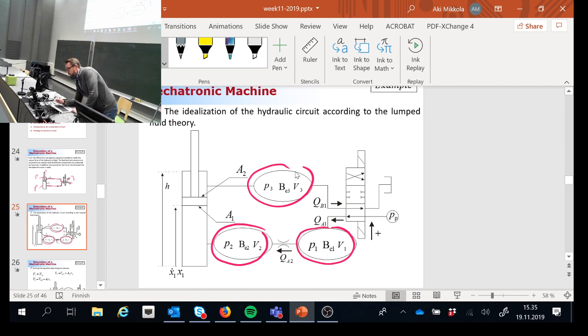The first rule is that whatever flow is coming off from the direction valve is assumed to have this positive direction. Whatever flow is going this direction through the throttle valve is positive. And whatever is going towards the direction valve has a positive value. Those are just the rules that I set. If you're not comfortable with these rules, go ahead and reset them, but be consistent. Okay?